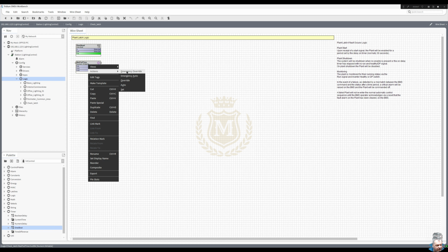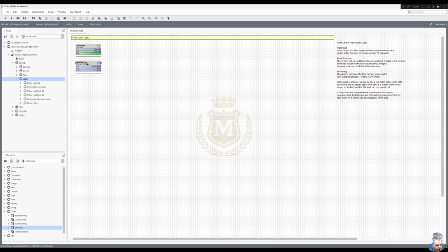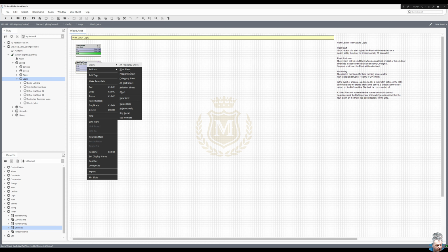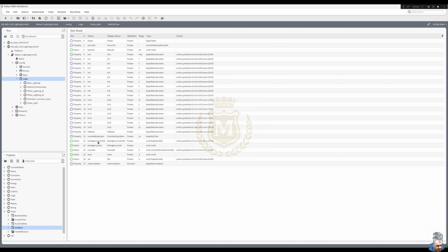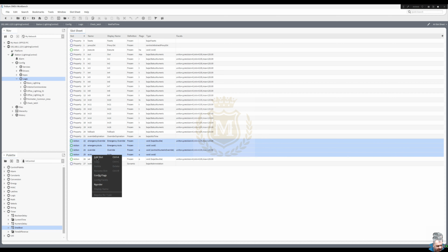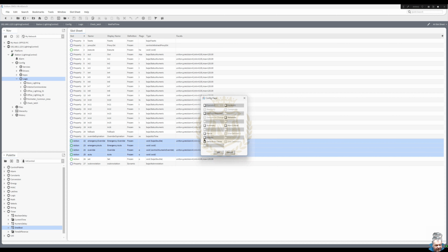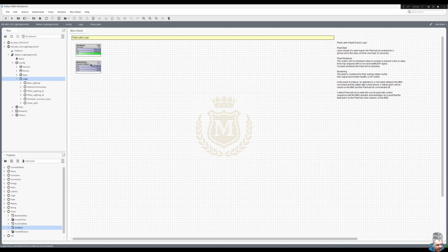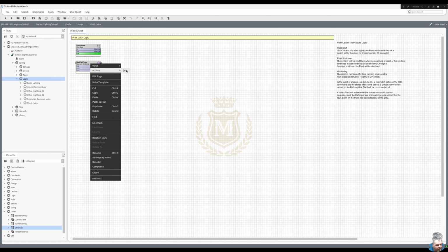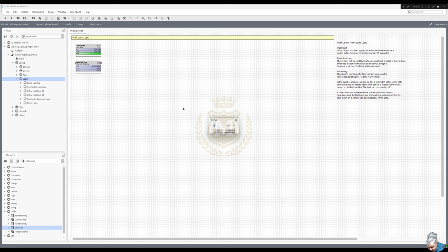I've got the emergency, so I've got these, I want to get rid of these. So views, AX slot sheet, highlight that, keep my finger on the shift and highlight, right click, config flags, hidden, OK. Action set, and we'll put that for 30 seconds for example.